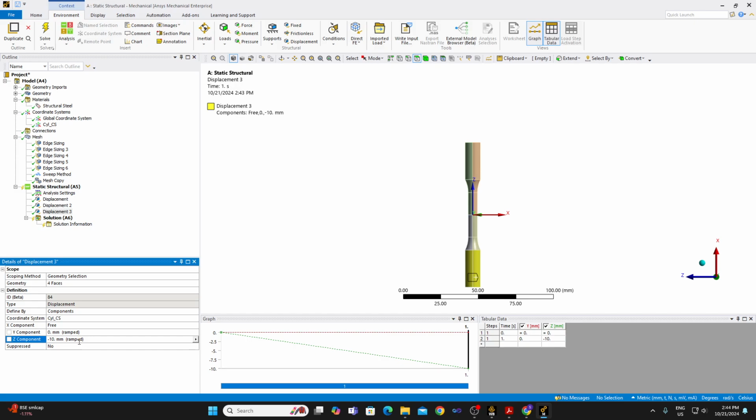See, in finite element, the boundary condition should prevent rigid body motions. And rigid body degrees of freedom, how many are there? There are 6 rigid body degrees of freedom. So 3 translations, 3 rotations should be prevented. Okay, at least 3 translations, 3 rotations.